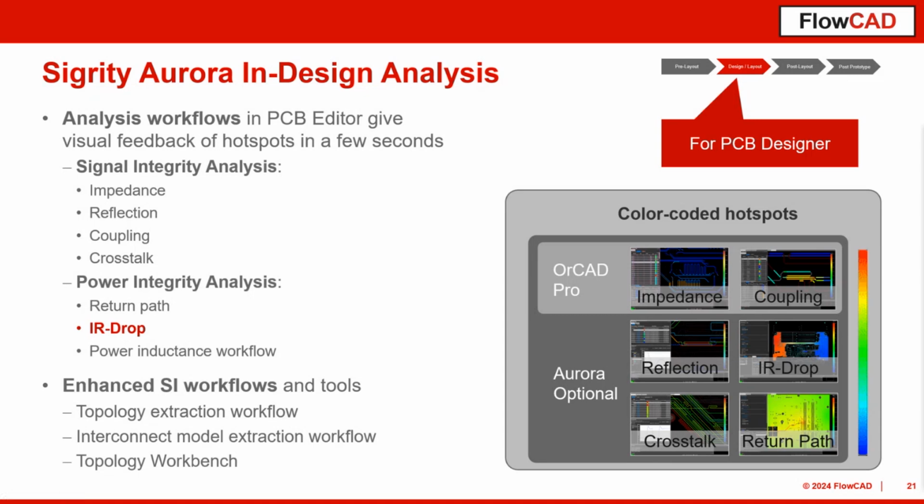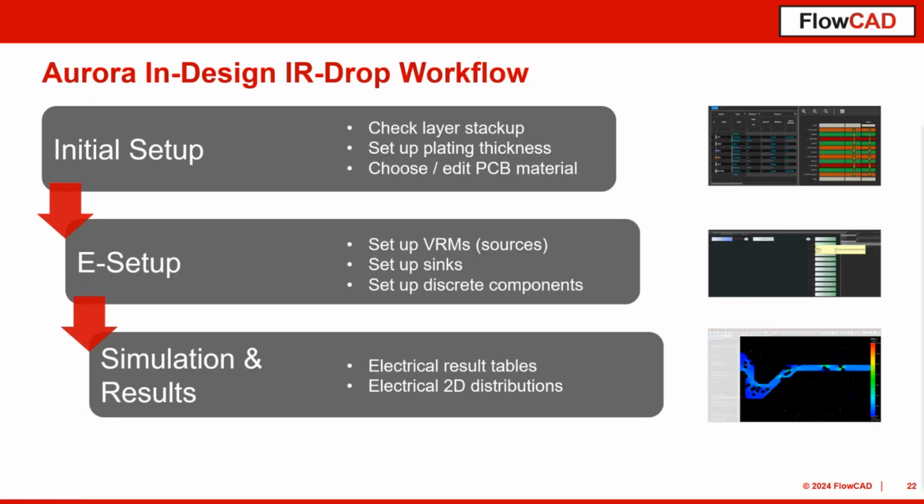So what is behind this IR drop analysis? What you do are a few steps. Starting from your design, you typically create your layer stackup. It is essential, of course, for any analysis. In this case, you also have to define the plating thickness for vias, for example, because this also has an impact on the simulation results.